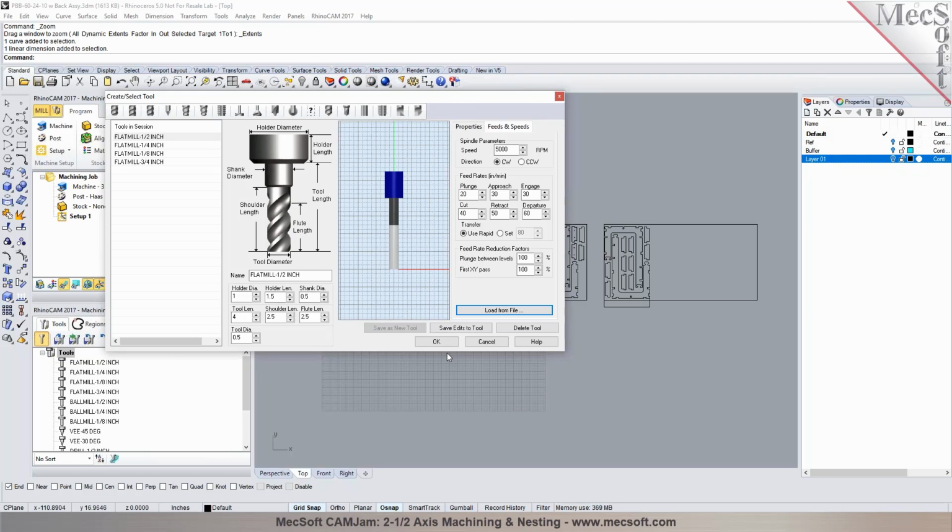I think the way you're doing it, you can actually customize your own, you put your own tool list in there. You've got to put your diameter in here, flute length, shoulder length, you define it. So these are the standard tool types like ball mills, end mills, flat mills, or square end mills, corner radius. So each of these, you define tools under each of these types. And then when you get that in there, you can freeze that so that we can apply it to anything we do from then on.